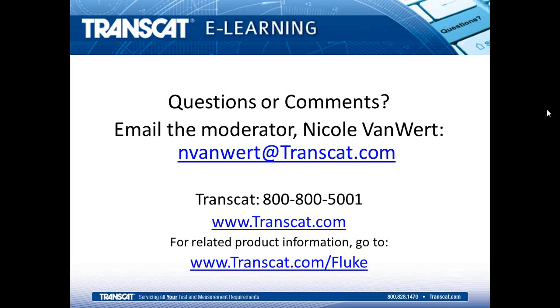Okay. Does the probe need to bottom out, or can there be an air gap? Yeah, it's a good question. It's okay for us to have an air gap at the bottom of a well, but as we talked about in the slides with immersion depth, we want to try to follow that 15 times the diameter plus the sensor length rule to help us to accommodate the stem conduction problems that we might get. But there's no need for it to be resting on the bottom. If it doesn't quite get there, that's okay. We just want to consider those other sources of errors that we talked about.